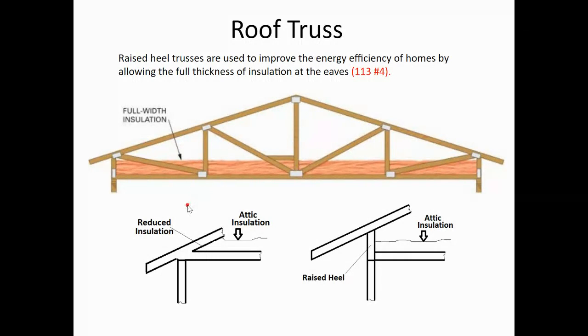All right, so to wrap it up, we know a little bit about the different types of houses. We've got stick frame. In the stick frame category, we've got balloon frame and platform frame. And then there were things called log frame or timber frame. And then we know the main parts, right? It starts with the concrete foundation. We have a girder.